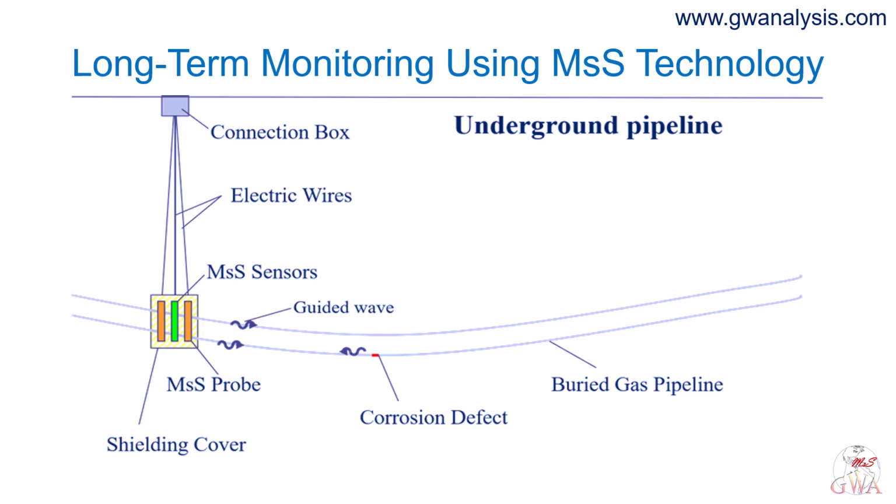That means you can detect a growing defect that is far smaller than anything you could call from a single inspection, because you are no longer fighting the coherent noise. You are finding only the difference between two measurements. That is the real value of a permanently installed sensor. It is that the same sensor in the same place turns a detection problem into a change detection problem, and change detection is a much easier problem.